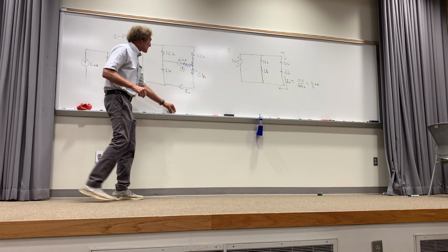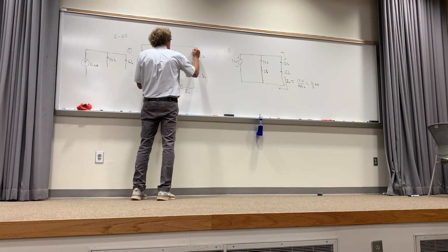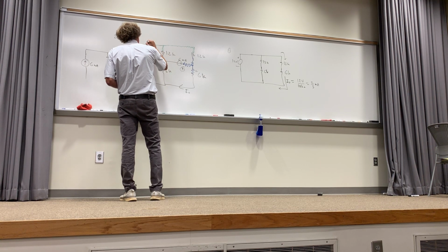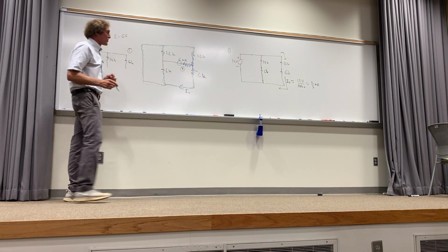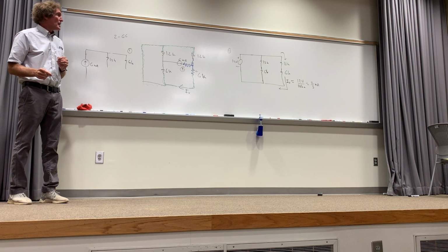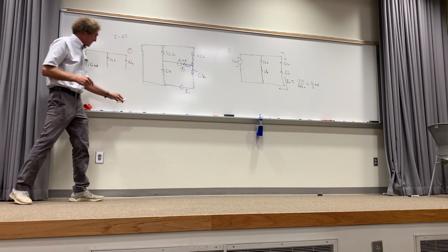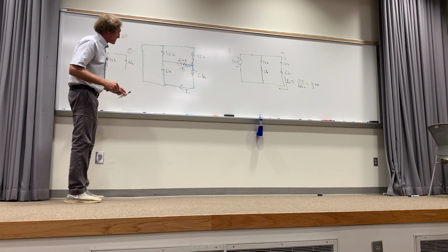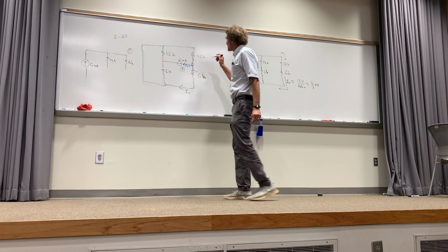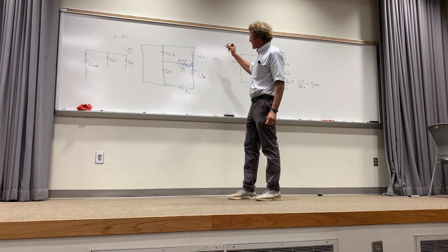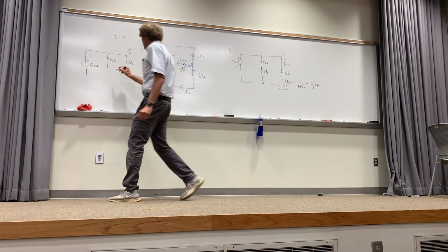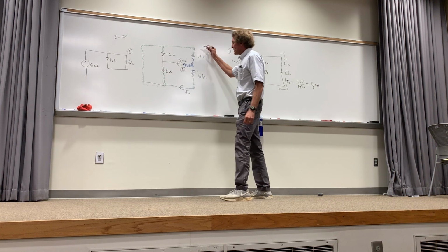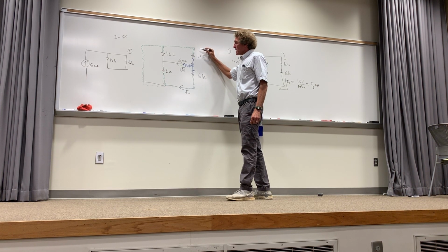Now I take a different colored marker, green in this case, and I go to the other side of the 12K, and I go through all the wires and touch everything. Everything between the green and the blue is in parallel. Can you all see that? Green and blue. I basically have this 6 and that 12 in parallel, right? They're between the green and the blue. Do you agree with me? Now those two are in parallel, and that's really where it stops.